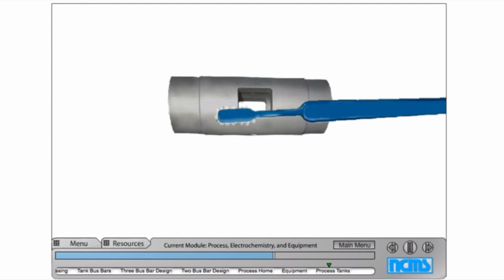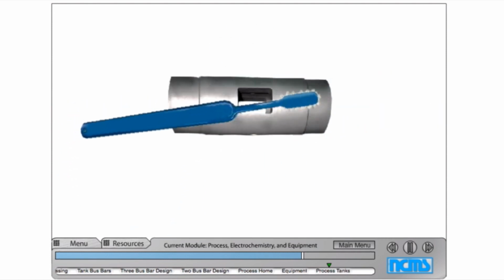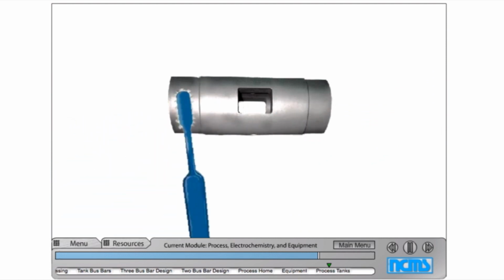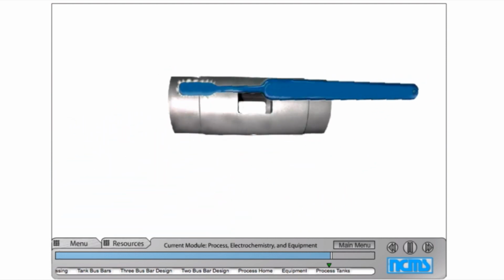Cleaning prior to plating is more critical than almost any other step in the plating process. The part to be plated must be cleaned very thoroughly to remove any grease, dirt, dust, or foreign material, which can interfere with plating efficiency and introduce contaminants to the bath.